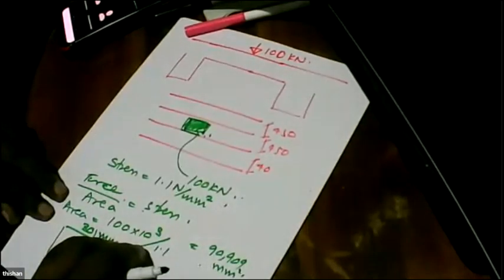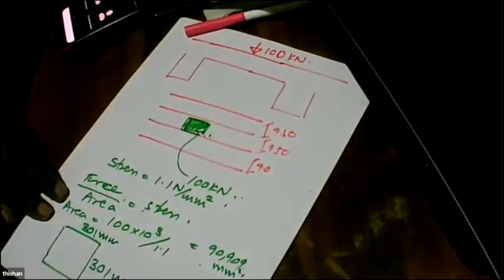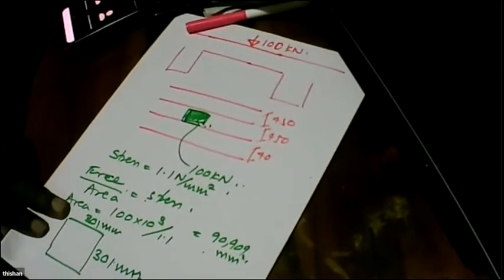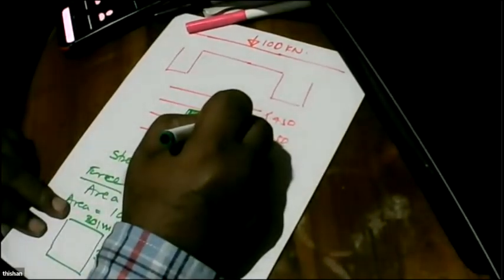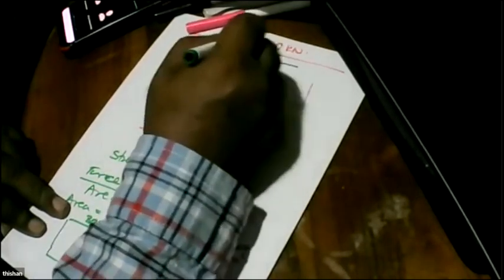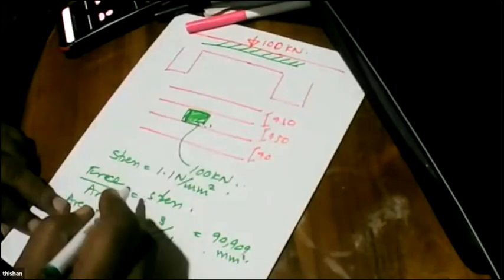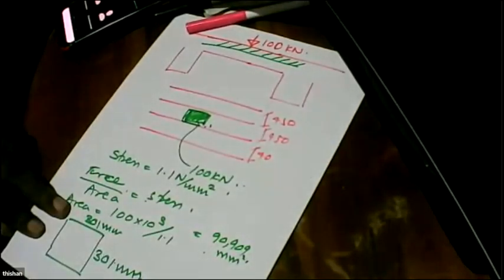Now you have a problem because this huge load is going to act on one panel, one precast panel. So what you do is, we have done some load sharing because we are going to have a screed concrete, and this concrete is there. So whatever the load will be, though these panels are separate, the loads will be distributed.